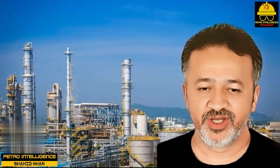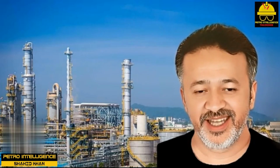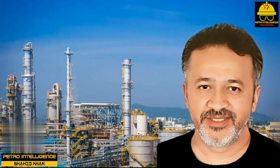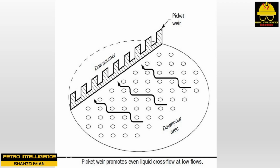components. Uneven liquid flow is promoted by the outlet weir being out of level. Liquid will tend to flow across that portion of the tray with a lower than average weir height. The portion of the tray upstream of the high part of the outlet weir will contain stagnant liquid. However, if the crest height, that is, the height of liquid over the weir, is large compared to the out of levelness of the tray, then an even liquid flow across the tray will result.